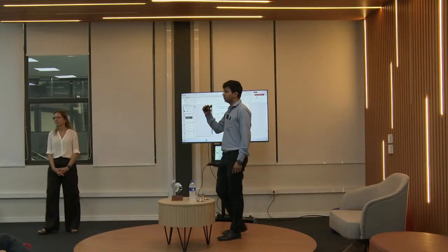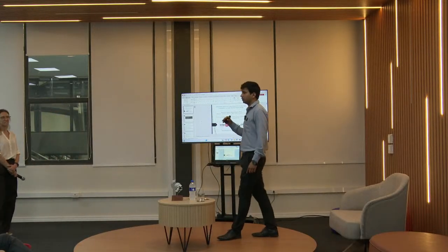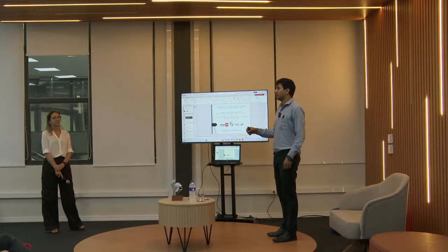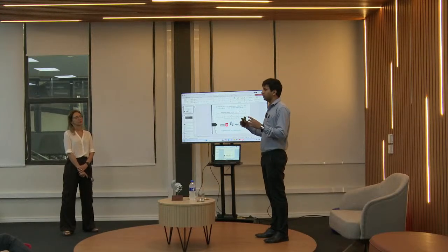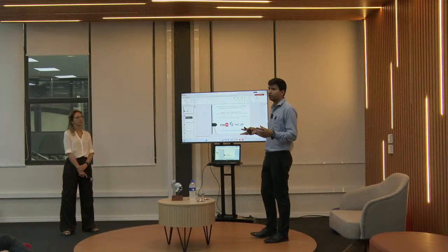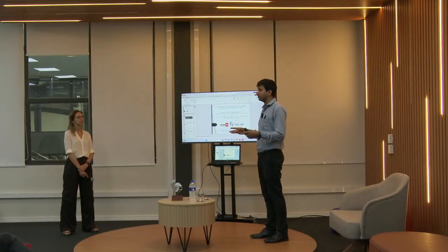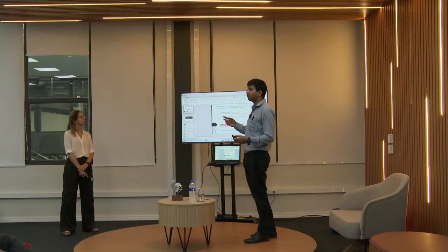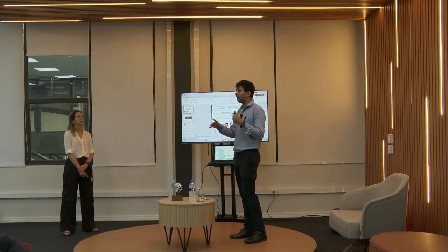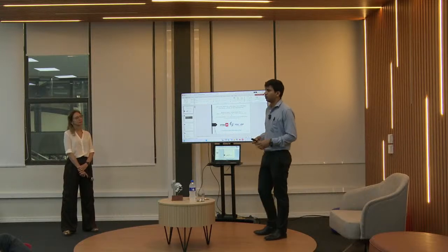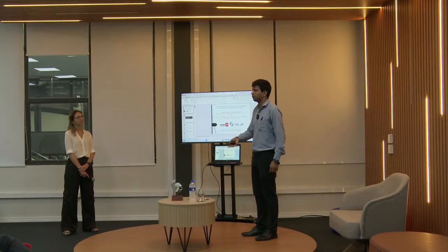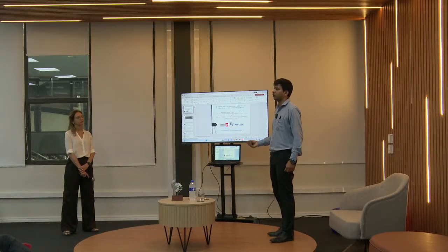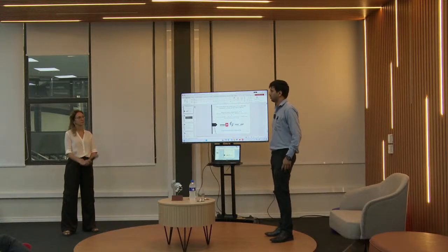As per the best of my knowledge, it's the bearing resistance of the helices, the helical plates. When we have helical plates and a shaft, the resistance offered by the shaft is negligible. So only the resistance offered by the helices of the pile or nail is the predominant factor, which provides the uplift capacity of the pile and the pullout capacity of a nail. Yes. Thank you. Thank you.